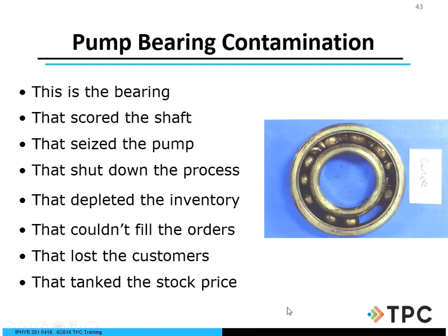turn as easily. So if your bearing's not turning as easily in your motor or your pump, what does that cause? We're talking about rotation, so then we need to talk about torque. If I'm putting too much torque within my system because my bearings are failing, I'm going to require more amps for my circuits. Now if I'm requiring more amps, and I've only got a 20 amp breaker, boom, I'm going to start tripping my breakers and so forth. So everything needs to work in conjunction with each other. These are important aspects within our whole hydraulic system.